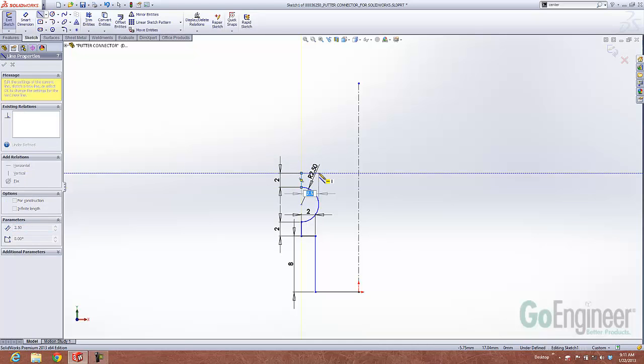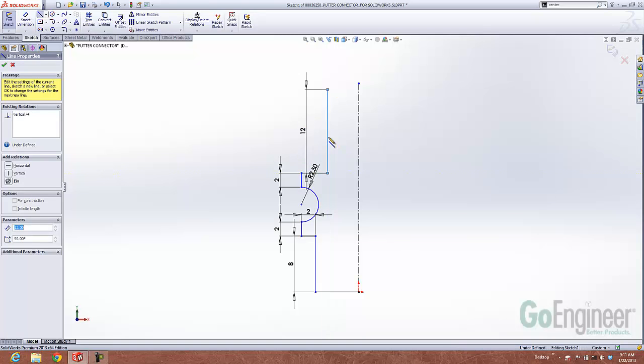We'll go in. In this particular case, I don't want a line segment because I'm going to do the double dimension again. So enter no value. When I place or left click to finish the line segment, it doesn't place the dimension. Go ahead and finish this off. We'll say this is going to be 12. And then we'll just close it up here.